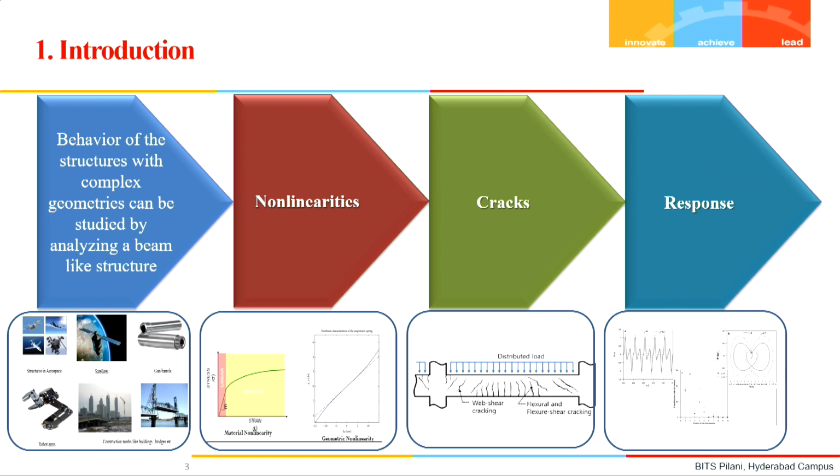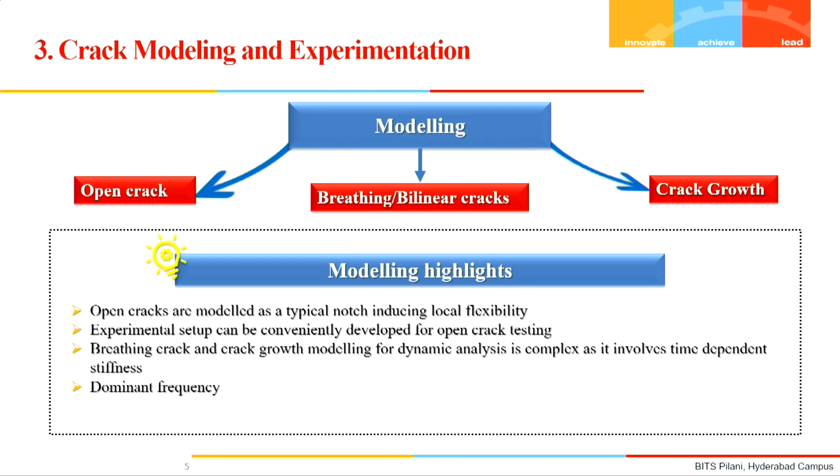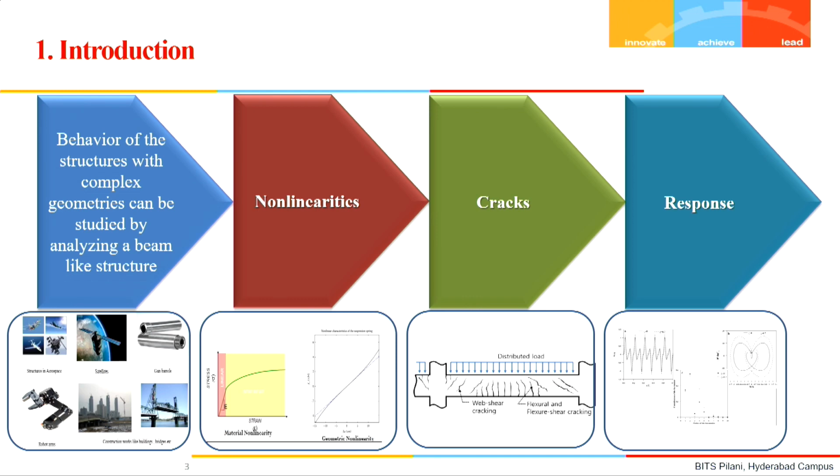We'll be talking about the effect of these cracks on nonlinear vibrations, because nonlinearity is inherent in these structural applications. The most accounted nonlinearities in structural mechanics are basically material and geometric nonlinearity. Material nonlinearity, as we all know, is where the behavior, the constitutive relations, are nonlinear, and geometric nonlinearity is basically about large amplitude motions where the induced stretching causes the nonlinearity. So we'll see the effects of these cracks on these types of dynamic behaviors.